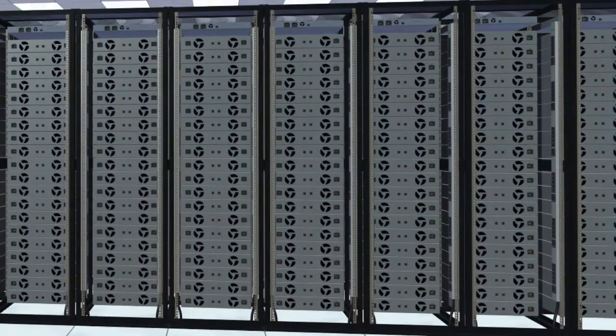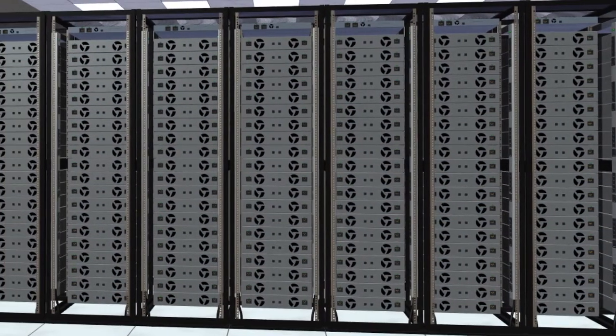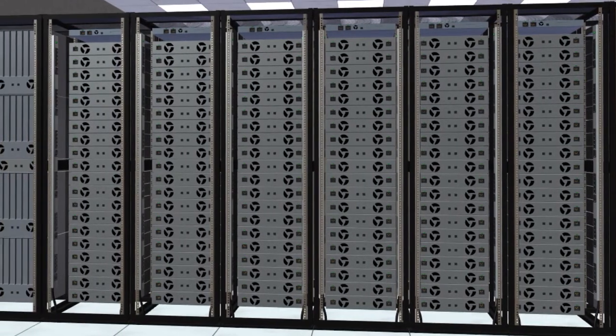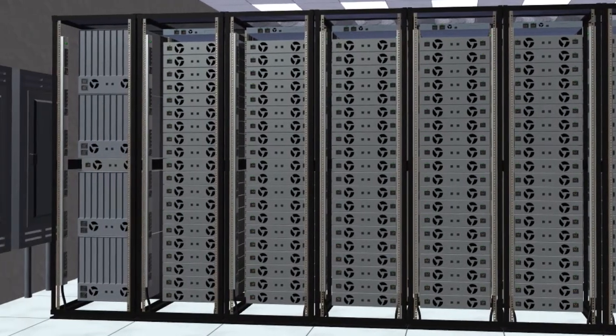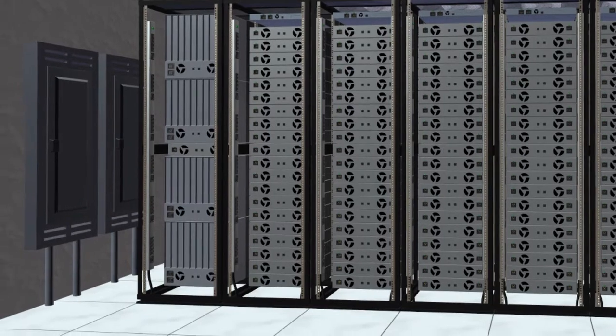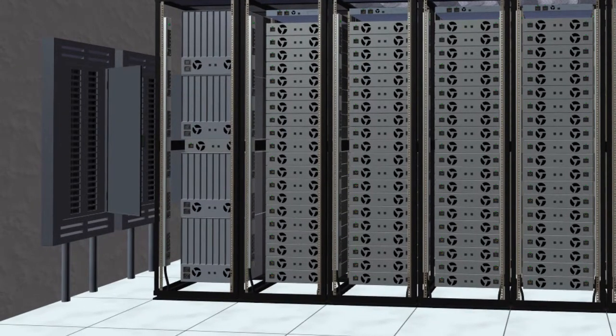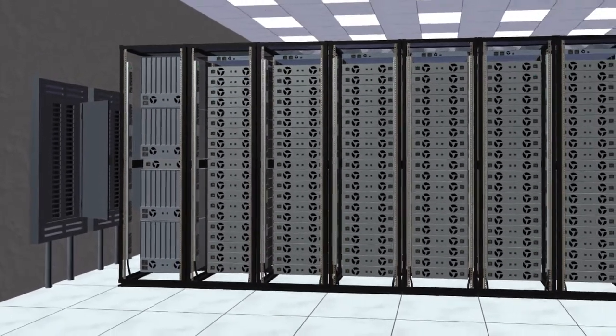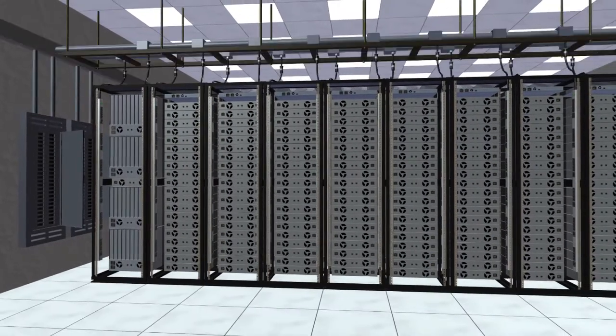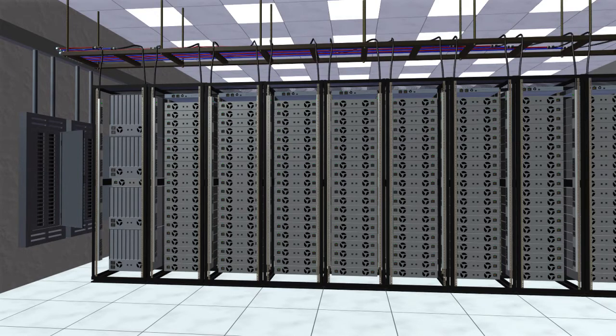Two traditional methods are currently used to implement redundant AB power distribution to the rack. The first method is to run power whips from the electrical distribution panel or panel board under the floor or overhead to the row of racks using either rigid electrical metallic tubing conduits or flexible metallic conduits.